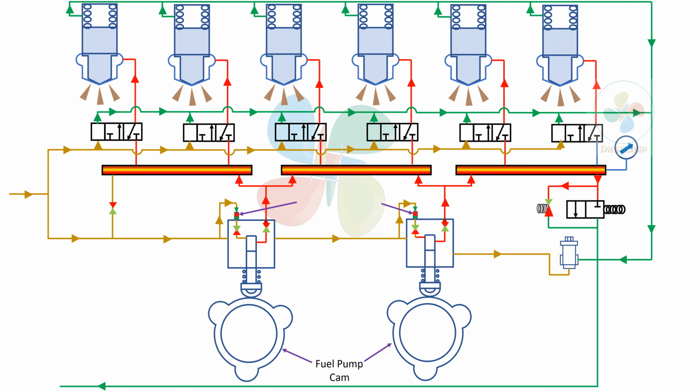And the next is the fuel pump. You see two fuel pumps. Obviously, we cannot have one fuel pump; we should have redundancy. But there are calculations depending on the number of units, amount of fuel required and pressure required, so the number of pumps may vary, but the minimum is two per bank, per side, or per engine if it is not a V engine. Right. The next component that we're going to see is the suction throttle valve, the throttle magnet.